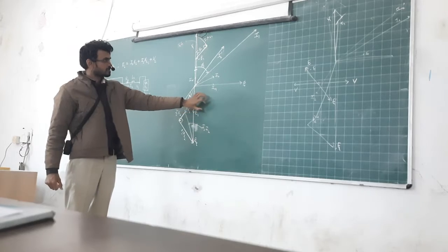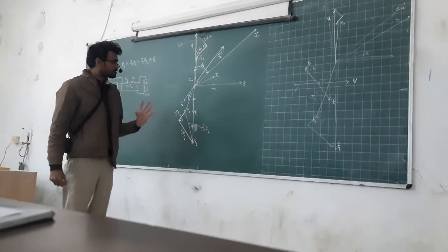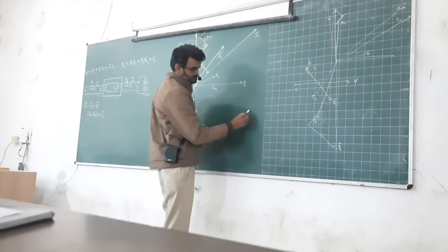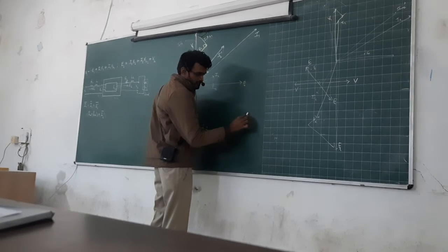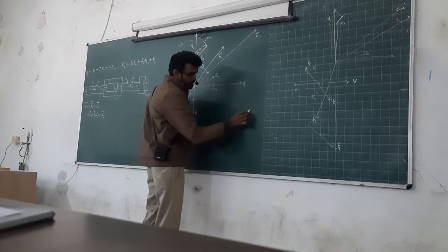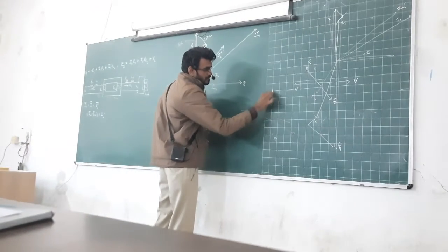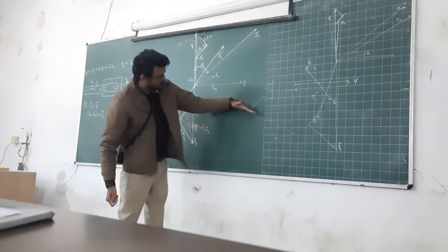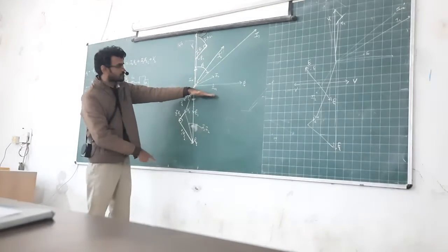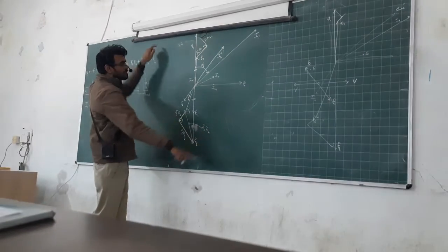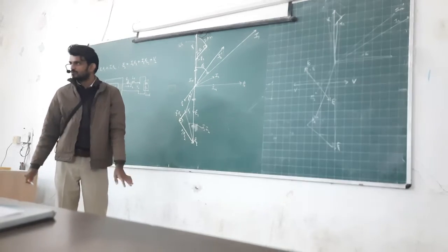These are the general steps to understand how to draw the phasor diagram. If you start the drawing of the phasor diagram by considering I0 in this direction, phi 0 in this direction, then you have to draw a perpendicular line here. Okay, then I0 here, V2, I2. Okay, add both. Here another vector. I2 dash and I1 added together, then E1, and here is the V1. So your whole diagram will be shifted in this way. If you start to draw I0 in this way, then the whole structure is shifted in this direction. You can draw this diagram in this way also, then the whole structure will shift in this direction. So in general we draw this line horizontally and this line perpendicular, even E2. In this way we will start to draw the phasor diagram.